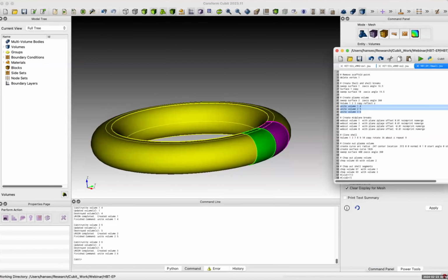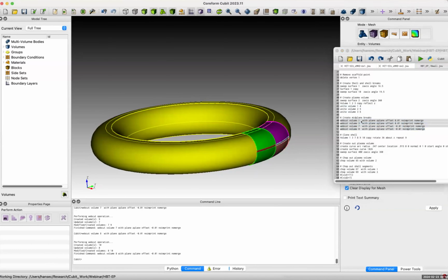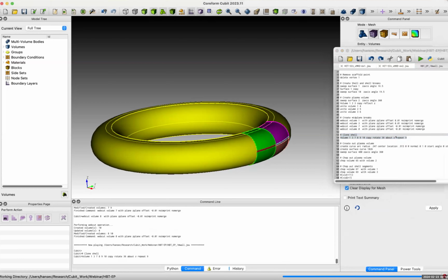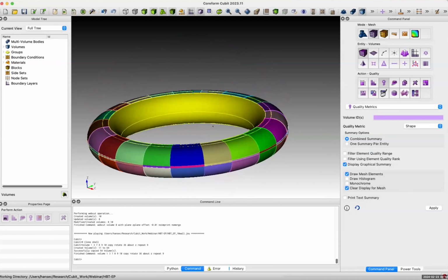All right, so to put in a little bit more detail, the shells top and bottom are actually slightly separate. So I'm going to put in breaks at the mid plane on the shell. I'm going to do this by using web cuts, a centimeter above and below the mid plane. And then I'm going to take this structure and clone it, just repeating it around the torus. All it is is repeating this 9 times around the structure, and I do that by doing a rotation. Okay, so now I have this whole structure built up with the shells, the alternating breaks, and the plasma region.